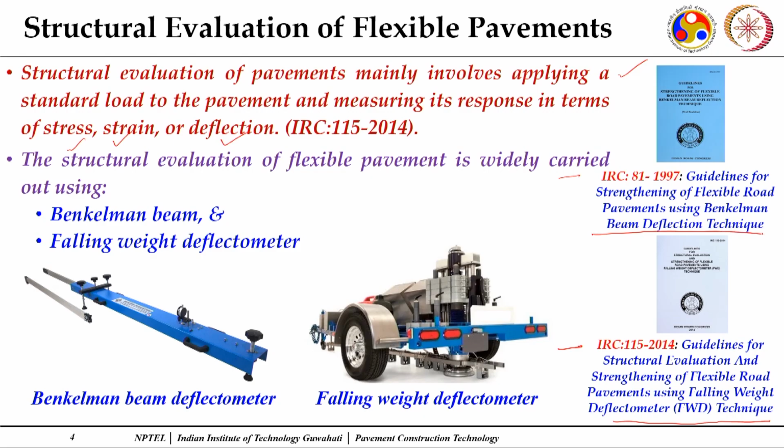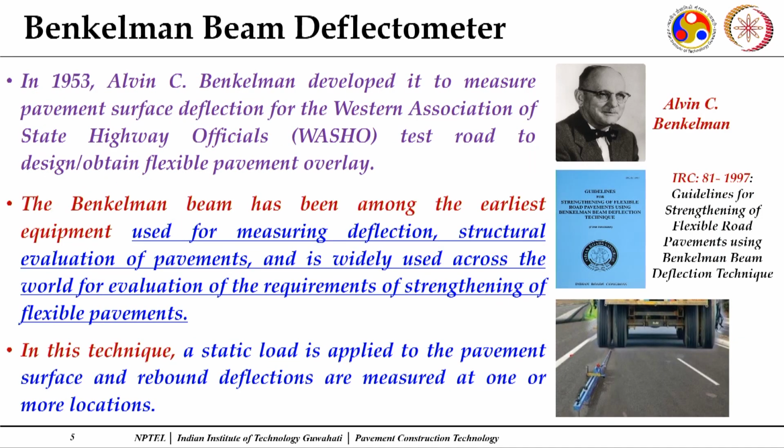Here you can see these are the two different techniques used for working out the strength and the overlay for strengthening of flexible pavements. Structural evaluation of flexible pavements is widely done using the Benkelman beam and the falling weight deflectometer, the two sets of equipment used for this purpose.